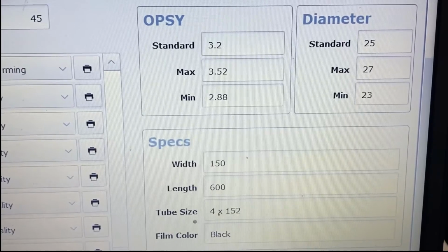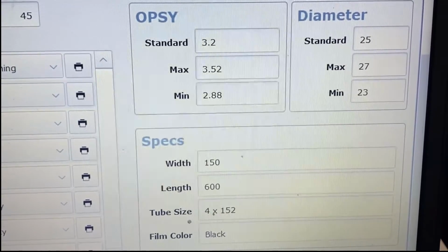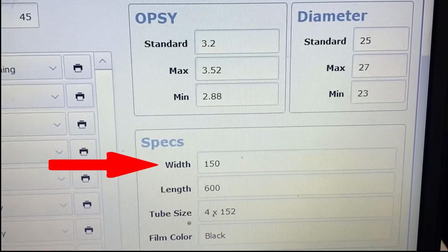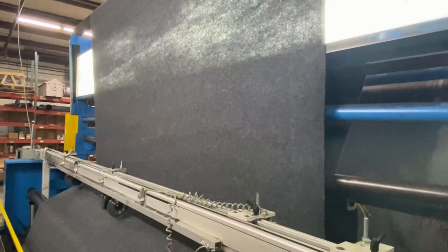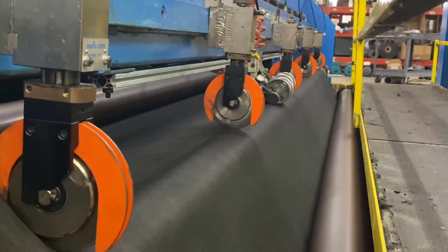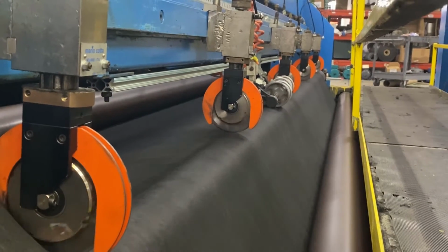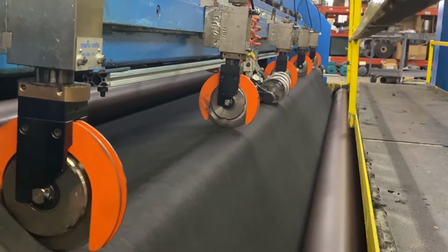Once the correct core length or lengths are at hand, identify the spec width of the product. In needle punch nonwovens, we optimize to the largest machine web width possible. In some cases, a single roll width may optimize our available machine width. But in other cases, we could potentially run up to 5 rolls wide and slit the rolls at our rotary or crush cutters to provide the target customer specified width.